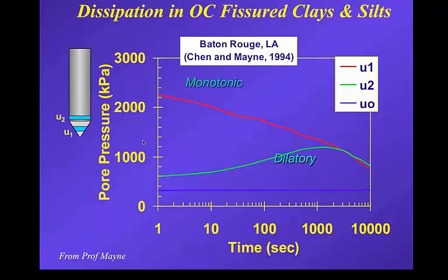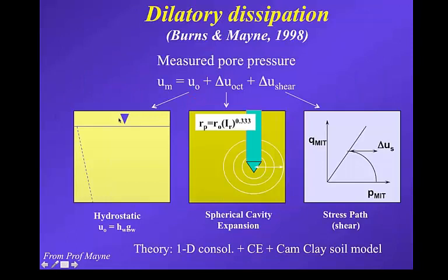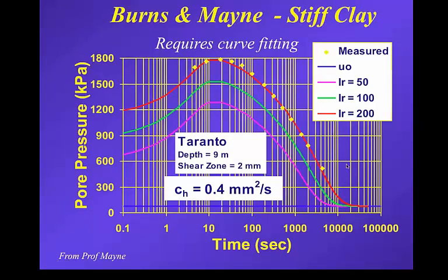So people have observed that when you measure pore pressure on the face, where it's dominated by the mean normal stress, you have a lot of shear stresses, but there's a very high mean normal stress, compared to just behind the shoulder, where the mean normal stress has gone through a reduction, and so it's dominated by shear behavior. And if the soil is stiff and is dilated, then you can get much lower pore pressures there, and they will initially rise up as you get localized dissipation, not truly horizontal.